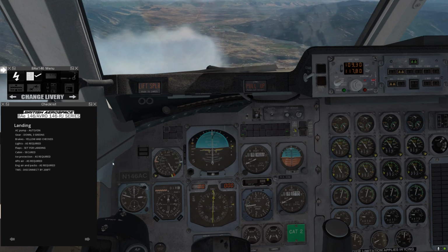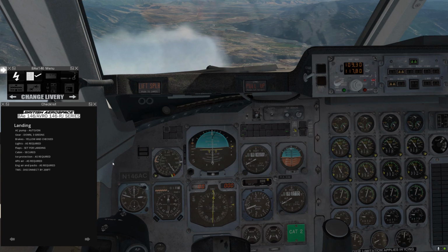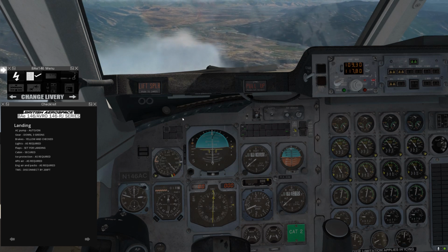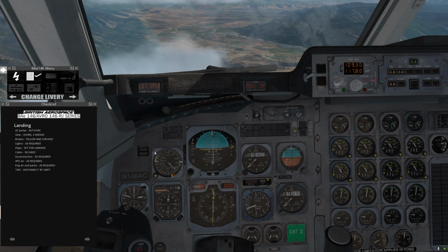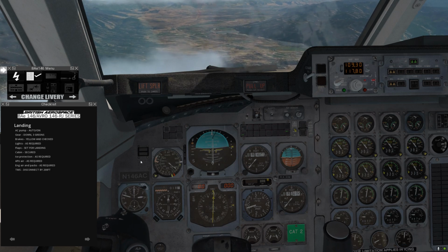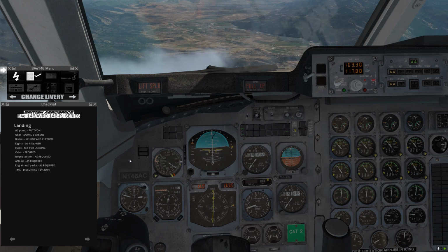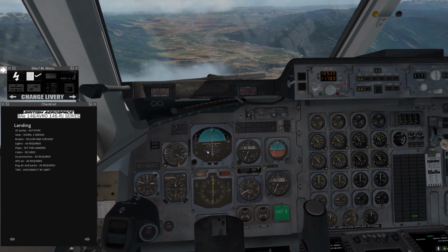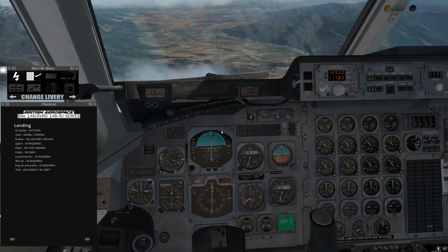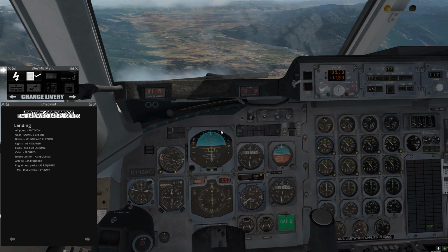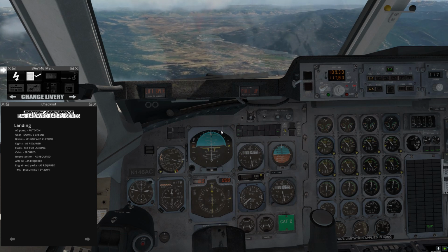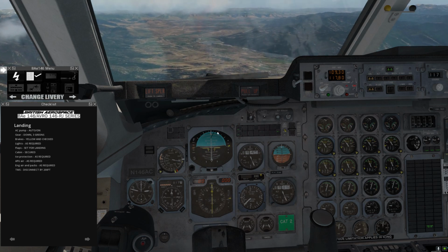So they're below 180. Below 160. Okay, and we'll arm the glide slope. Here we go. We are coming down on the localizer now. And below 145 we can go full flaps. Now that autopilot is having to use pitch trim quite a bit to compensate for those flaps as they extend, which if we were not using autopilot, manually we would have to be rolling that pitch trim quite a bit.